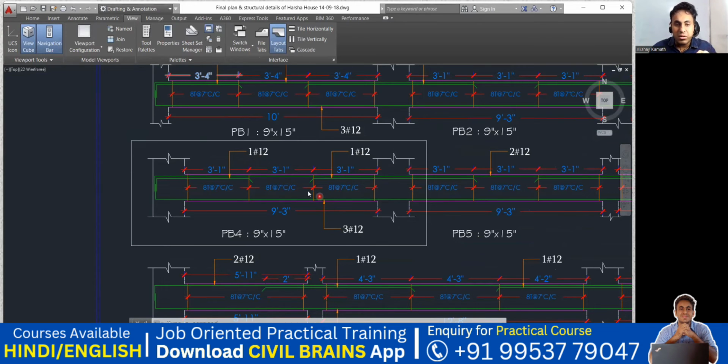Where is my main bar? I guess they have not shown that main bar. So this is actually your 12 diameter bar. This is also your 12 diameter bar. At the bottom, you have to provide a 12 diameter 3 bar. This is actually a 12 diameter 3 bar. I think they have missed it out. They haven't shown it. This is also 12 diameter 2 bar, and plus one extra bar will come.